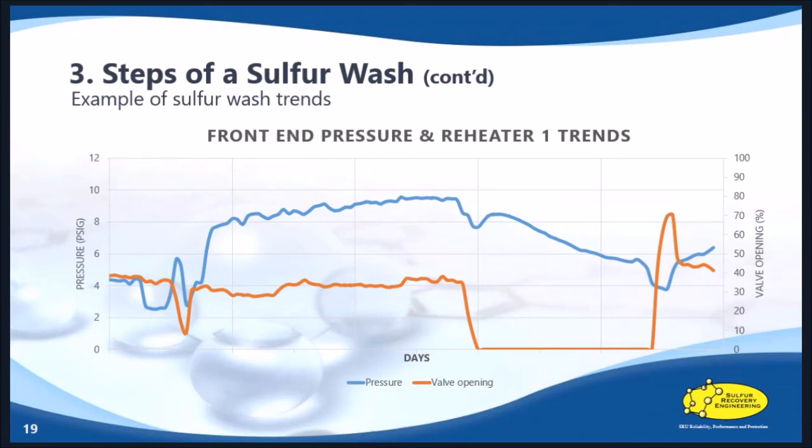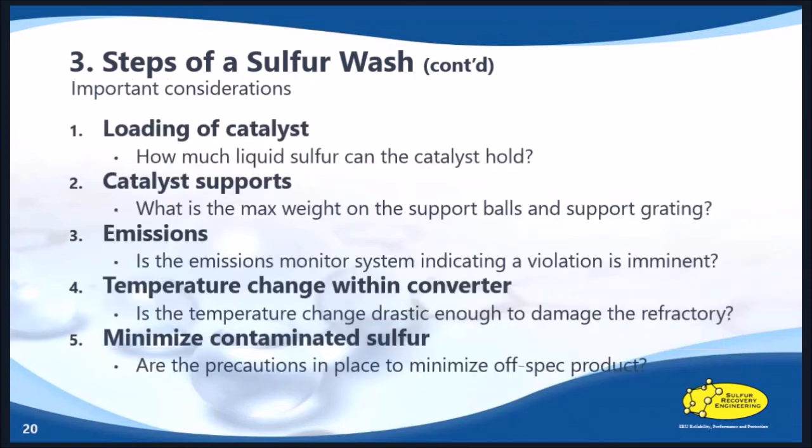Again, it's really good to have these graphs in front of you in order to illustrate what you will see once you do your own sulfur wash. Finally, with respect to steps of a sulfur wash, there are some really important considerations that you need to keep in mind. One is, how much liquid sulfur can my catalyst hold? It's a question you can definitely ask us. With respect to your specific situation, we'll be able to give you an answer. Catalyst vendor is definitely another one that you can ask that question.